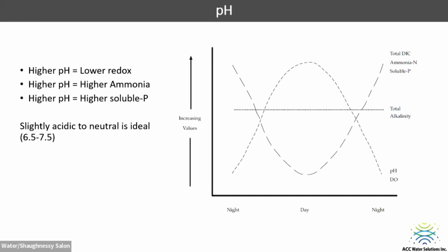We see this a lot more when we're dealing with wastewater, where it's more amplified. And it's a bigger concern because the wastewater operators are trying to keep their unionized ammonia low. Algae, as Dhaval mentioned, is the primary driver of pH changes in water bodies, or it can be macrophytes as well. Plant growth can cause it as well.